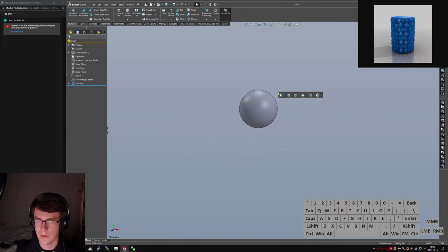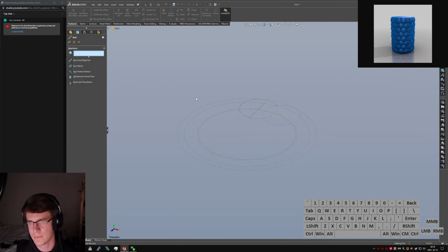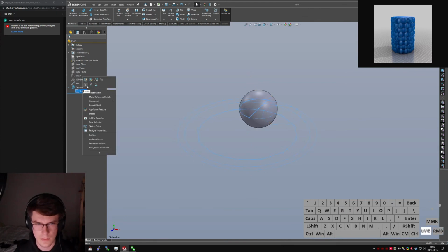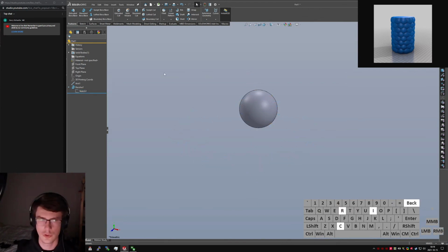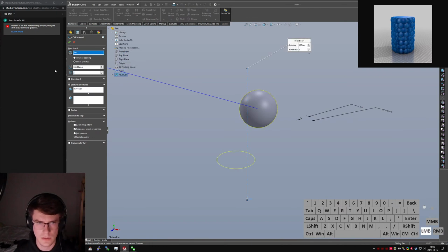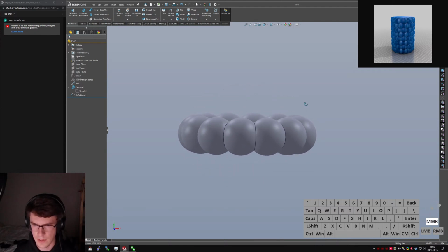Cool. Now, I forgot to draw an axis, so we're going to do a quick Control-T so I can move back before the feature. Say, show me the sketch. Well, it's going to be the front and right planes. It doesn't really need to be in any particular spot. So we'll hide that again. Then, circular pattern. Direction 1, about the axis. 12. Cool. Now I have to figure out...